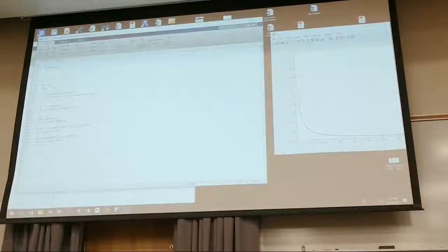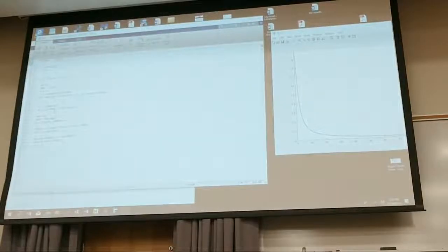Now, that's one. There's several others I did. Now, if I take this signal right here, suppose I take this times a cosine of, say, 10 times t. What would you expect to happen if I did that? Think about the natural property of modulation. What does modulation do? It takes the original Fourier transform and displaces it or centers it out at a frequency of omega naught. What is omega naught? Looking at that? 10. Do you follow me? Let's see what happens.